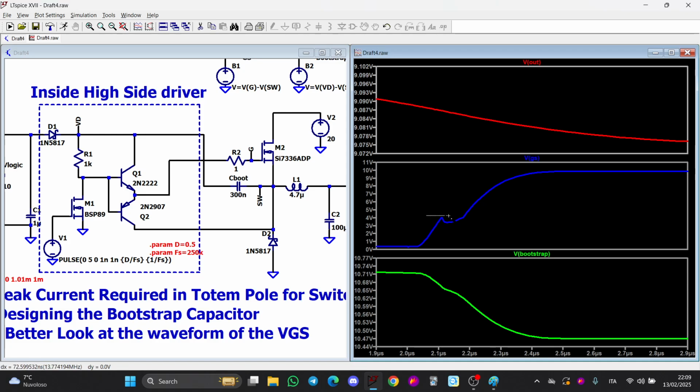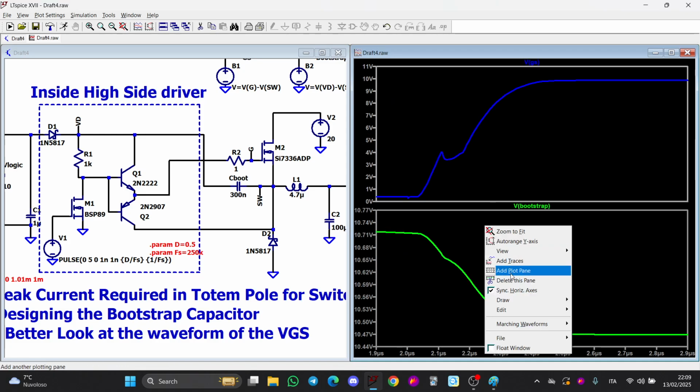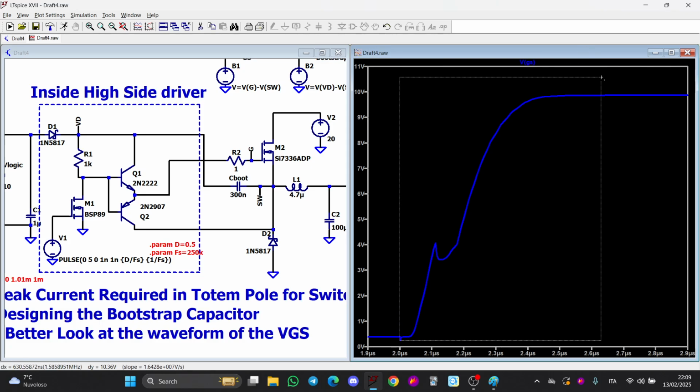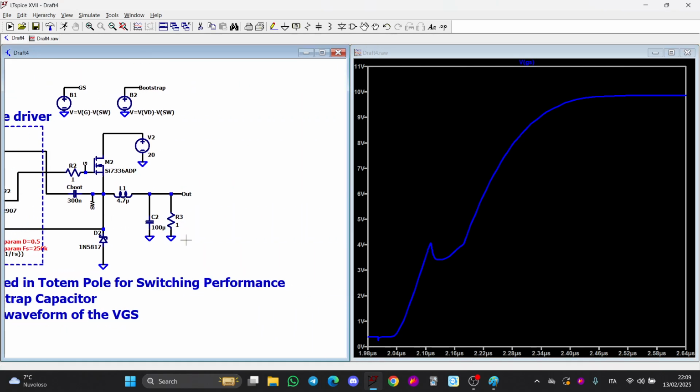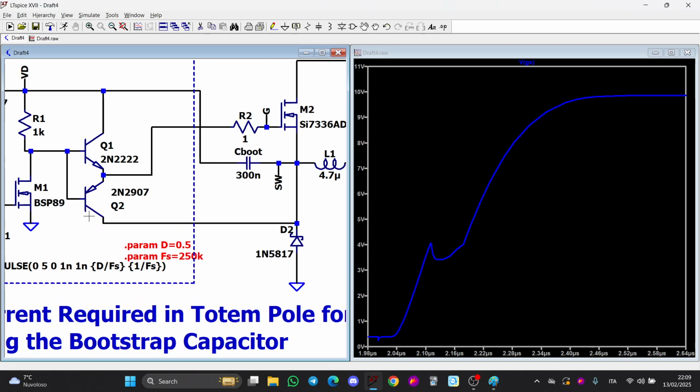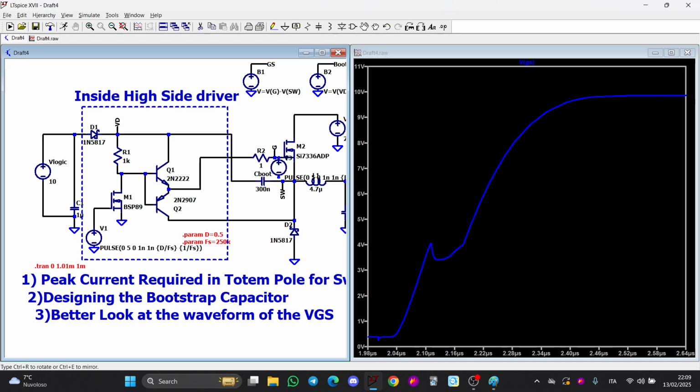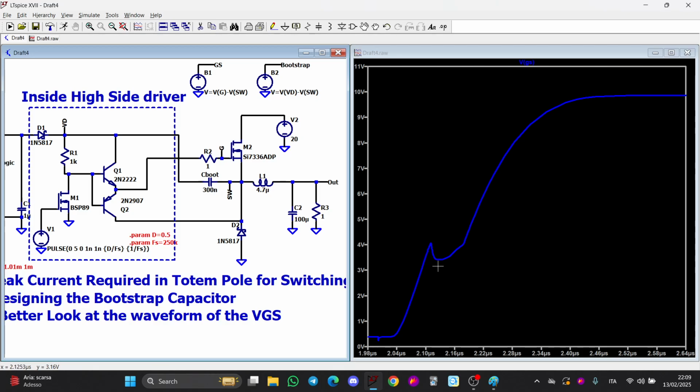So if I open the datasheet, as you can see, if we look just at VGS, can you see the Miller plateau voltage? It's beautiful. But if you do the LTSPICE simulation with just a buck and you put the VGS like this, you are losing this information. You are charging your MOSFET in current basically. You are giving current to your parasitic capacitance, but you're also giving the correct PWM. And for this reason, you see the true charge of your MOSFET.